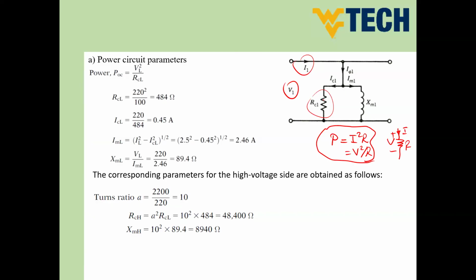If you have a look here, guys, do we have the current flow in this resistor? Actually, no. The open circuit current we have is I1. We don't have IC1. However, we have V1, which is the applied volt across RC. So we cannot say P equals I square R here because we don't have the current. But we can use the voltage V1, which is the open circuit volt, because this is the applied volt across the resistor, in order to get the power across this resistor.